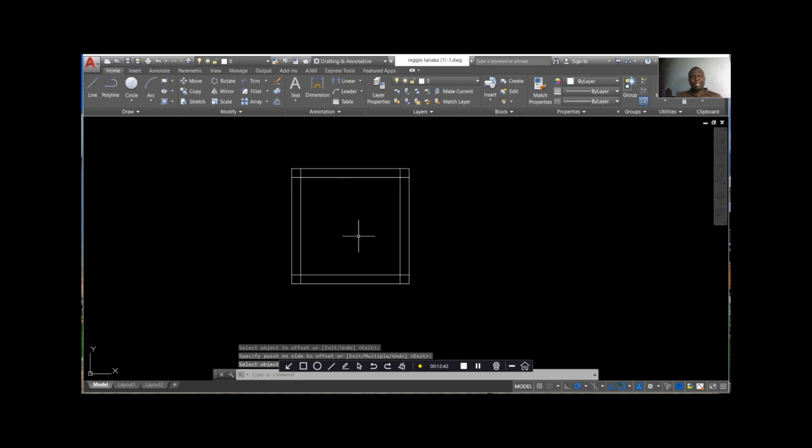All right. As you can see, now I've come up with this, but what I need to do now is trim, because the walls have to be continuous, not to have this corner. The walls have to be continuous like this. Then it shows that it's a room, a continuous room like this. I've trimmed all these lines that I was trimming.